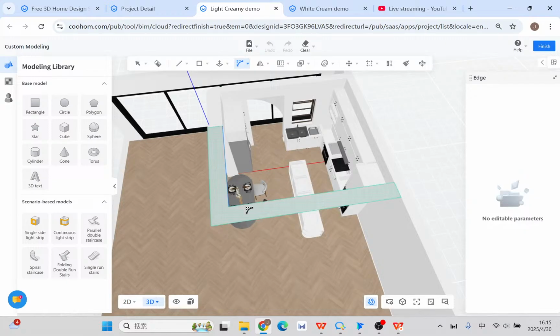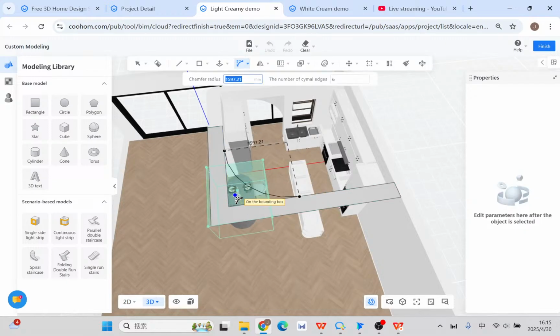Click the line, click the line. From the very beginning, don't forget to change the number of the small edges. The default setting of 6 is definitely not enough. What you need to do is make it really smooth. So still using the tab, change this index, and then let's turn to something like 30 or 45. It's actually enough around that.